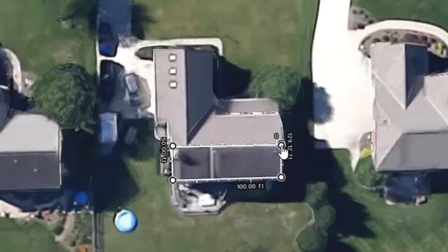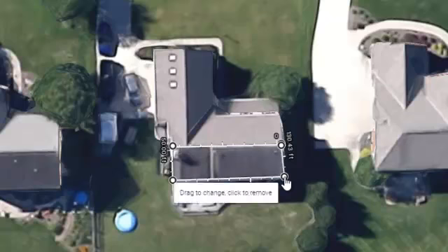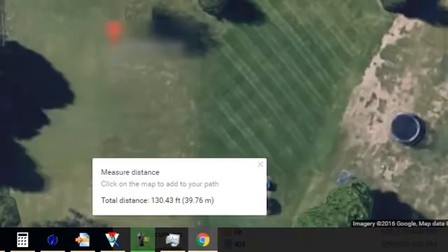You can do this by holding down your mouse and hovering over the starting point. You can also grab any of the measurements and manipulate them to align and/or straighten out the measurement for more precision. Once you have aligned and refined the measurement points, you will see the square footage of the roof surface. We will be copying that number to capture it as one of the figures for our total square foot area.